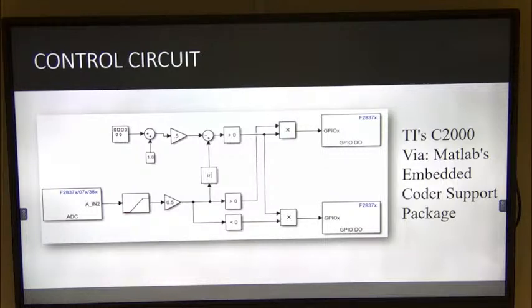As you can see, there are less than and greater than 0 blocks, which indicate that we have both positive and negative PWM signals. This is so that when you have the sinusoidal signal, the positive PWM is synchronized with the rising of the sinusoidal wave, and the negative PWM signal coincides with the negative or lowering of the sinusoidal wave.